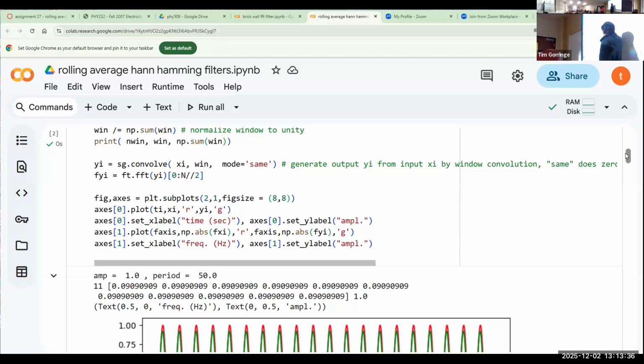So that's one way of dealing with the bookends, basically, on the far left and far right of your digital trace. There are other ways to do it. You can say, well, I'm not going to go right to the far left or the far right of my input. That avoids the problem of having to pad, but it means that your output has fewer samples than your input. That's the disadvantage of that approach, and that's a different argument. The one I picked is just to create an output that's the same size as the input, by this padding technique.